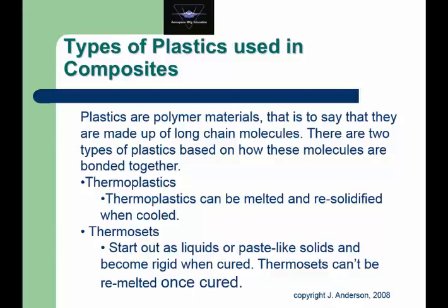And so they're held together typically by mechanical interference between the polymer chains and by van der Waals forces, or secondary bonding, which is similar to gravity. So if we get two bodies close together, they have a mutual attraction. Well, these molecules are small, but they're very, very close together, and so we get an attraction to each other that's similar to gravity.